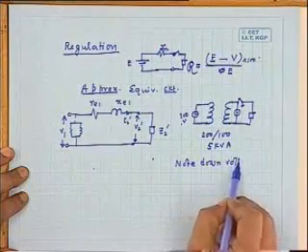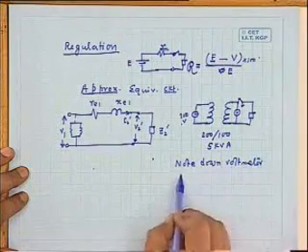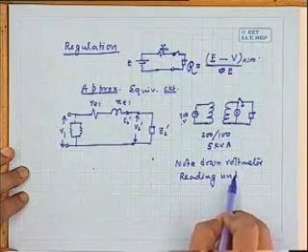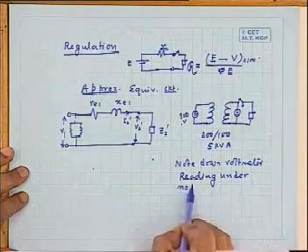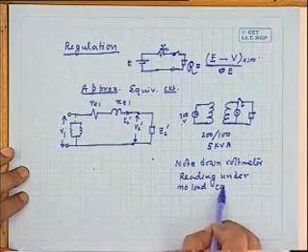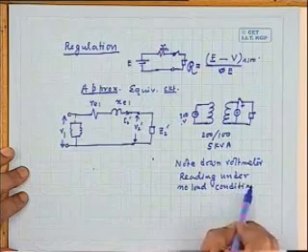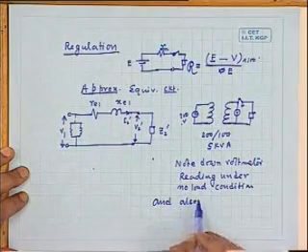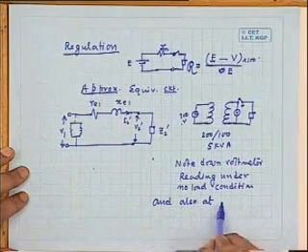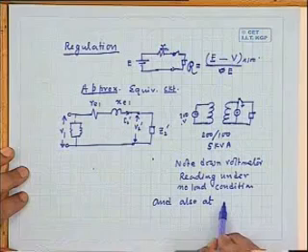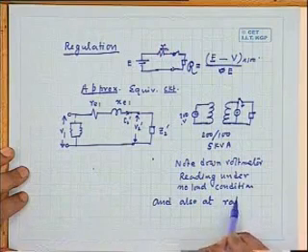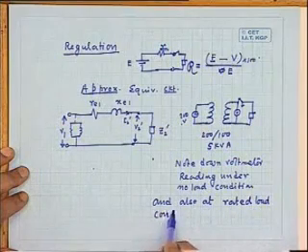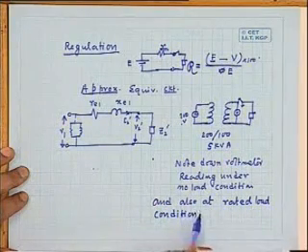So note down the voltmeter reading under no load condition, and also at rated load condition.